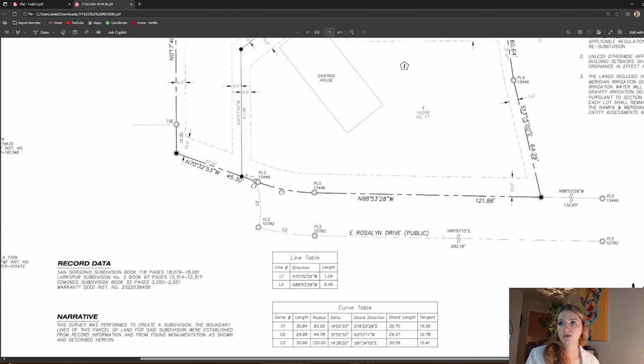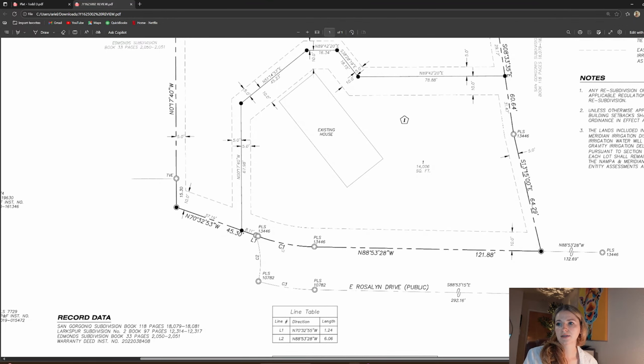So if I were doing this one, I would do all these lines, and then I would draw this C1 over here just to make sure that when I put all those numbers in, if I accidentally clicked clockwise when it needed to be counterclockwise, it can be completely shifted around from the direction that it needs to be, and I may need to input it again. But when I input it, if it looks to be the correct curve, then I just point to point move it, and it almost always matches up perfect, and then it all just closes in the polyline for you.